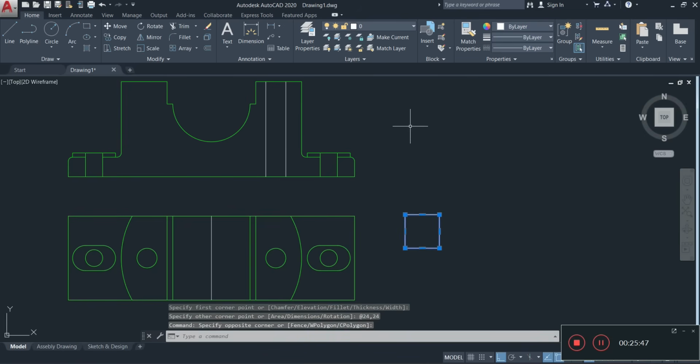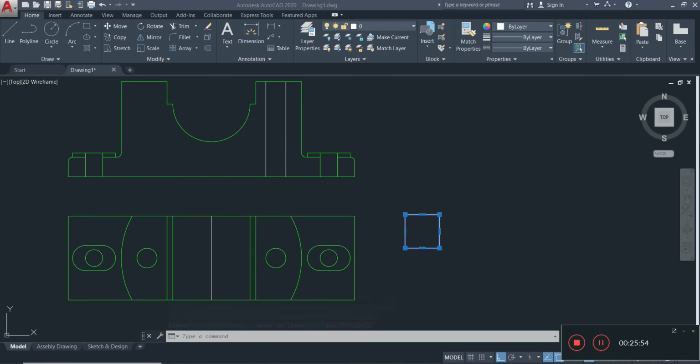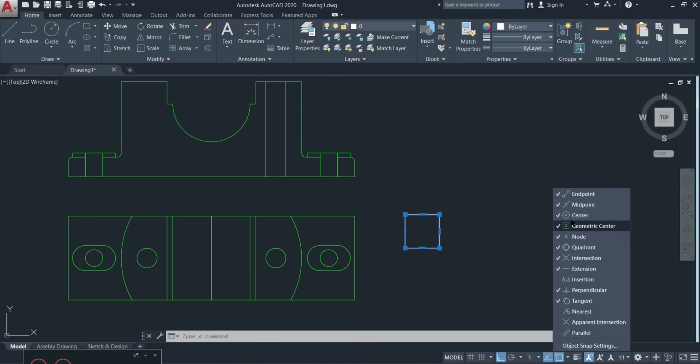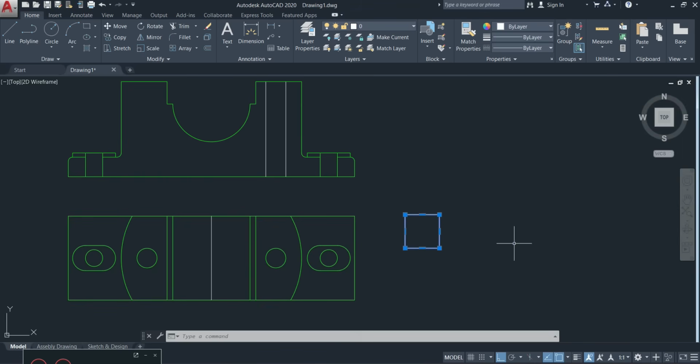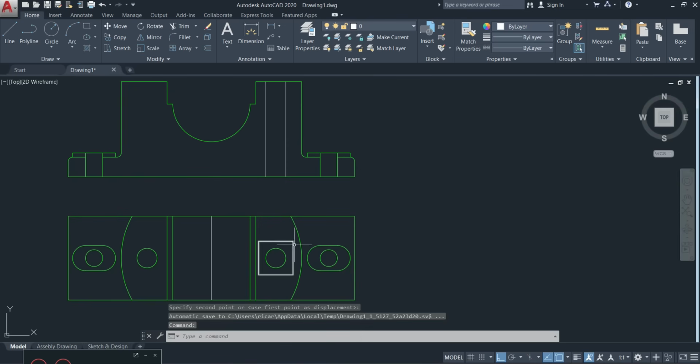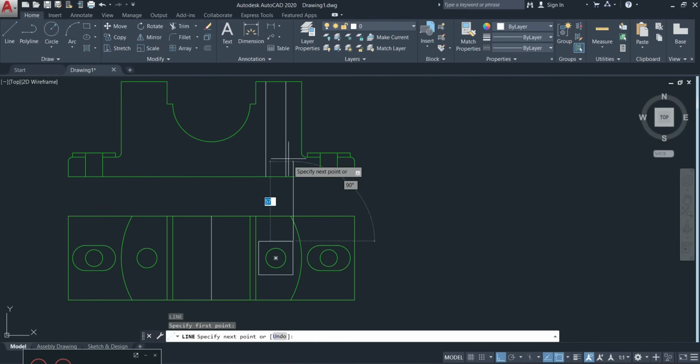Then now I'll grab it. Now if my snapping feature, let me push this to this side here. Alright. I'm going to ensure that my snapping feature that is called geometric center is on. Yes. So I'm going to be moving this. Hopefully I can find the center, and I'm going to place it right in the center there like that. Alright. Now once that is done, I can now project lines up for that right there, because that's where it should be.